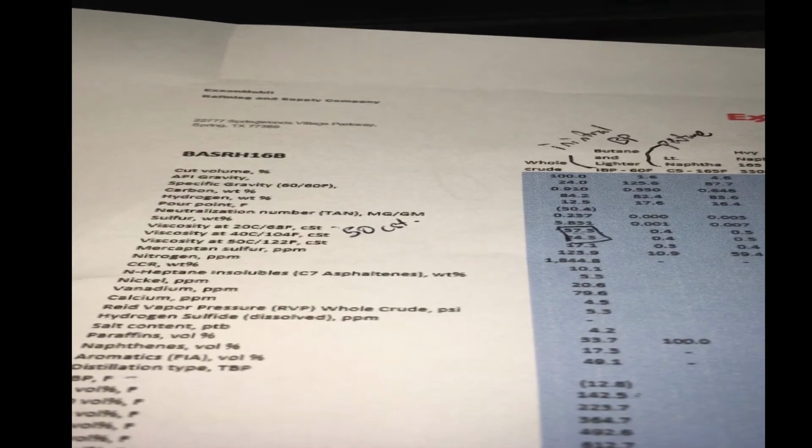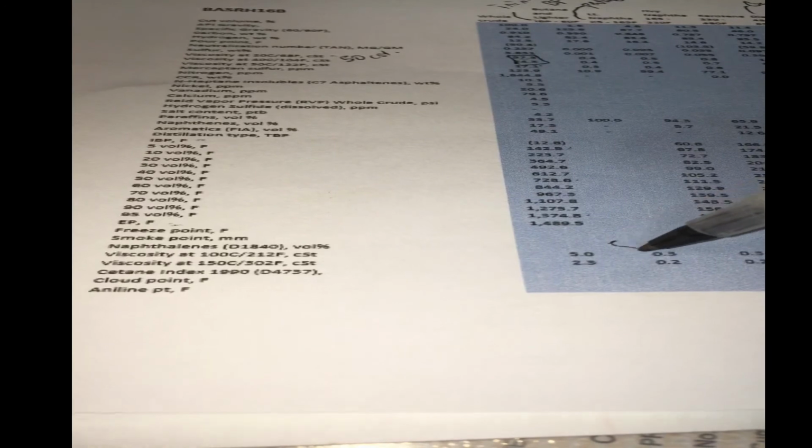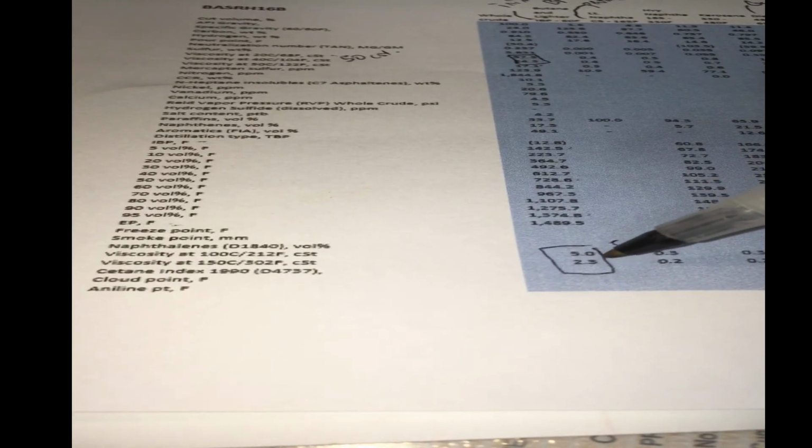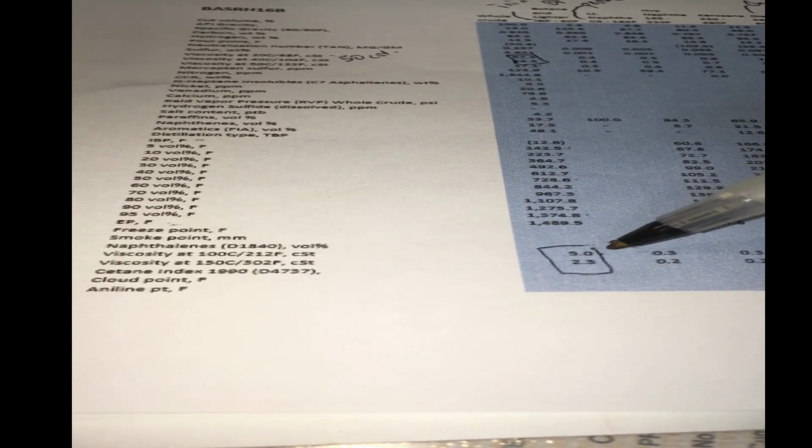And you see, as you heat up the oil, the viscosity decreases. And if you heat it up beyond 100 degrees, you see the viscosity of oil drops by almost 10 times. So at 20 degrees, you increase 80 degrees of temperature, you have a drop in viscosity of around 10 times.